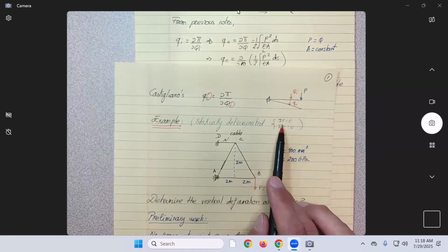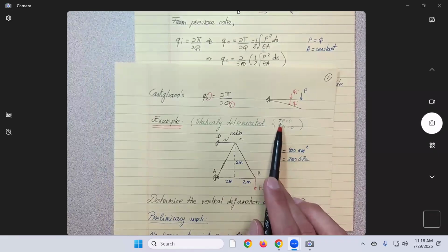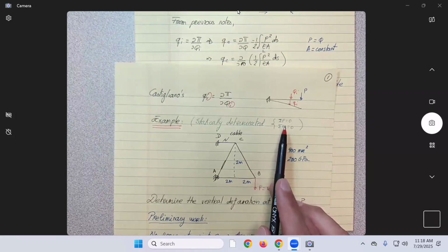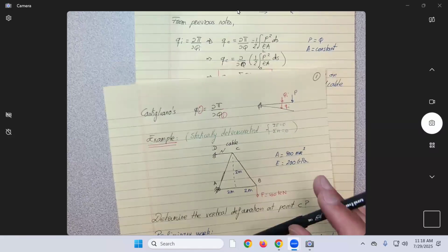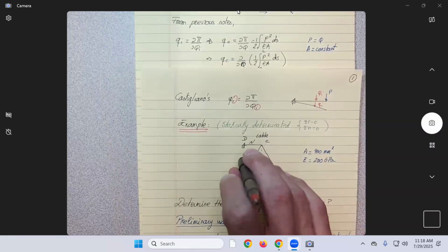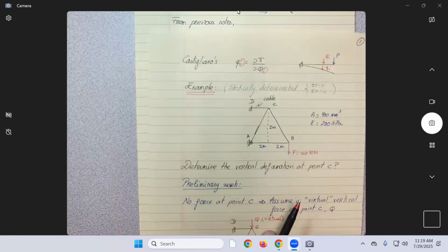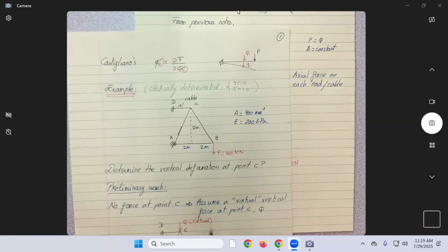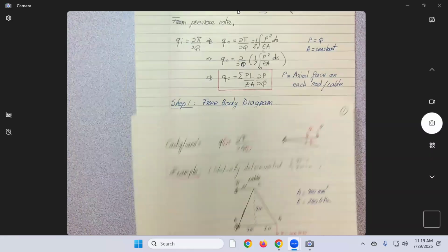For a 2D problem, how many equations do you have from the forces? 2, X and Y, no? How many from the moment equation? One, only the one coming in or out of the board. So the total number of unknowns you can have is 3.